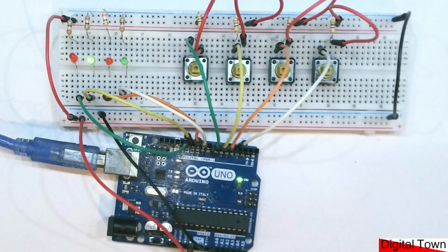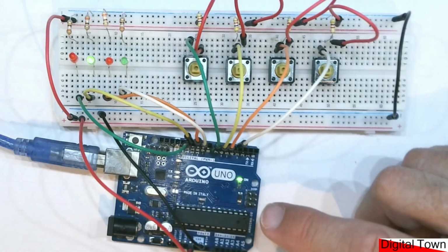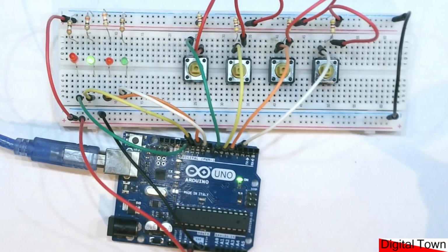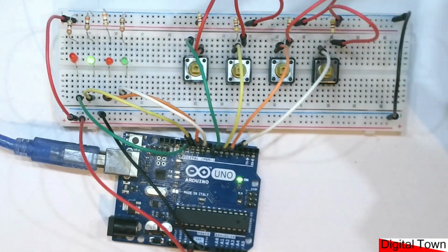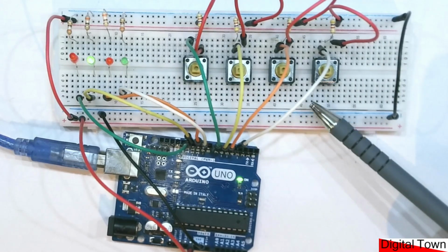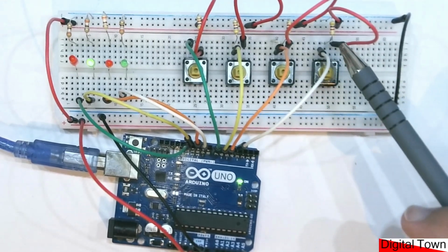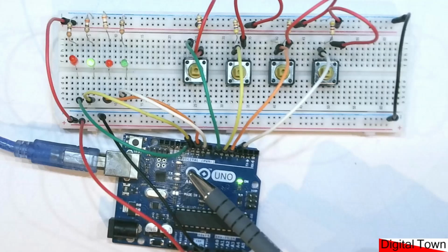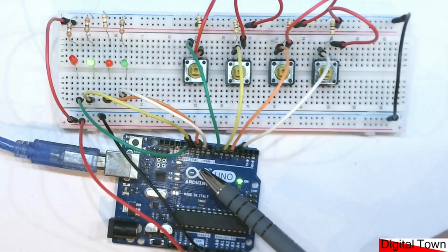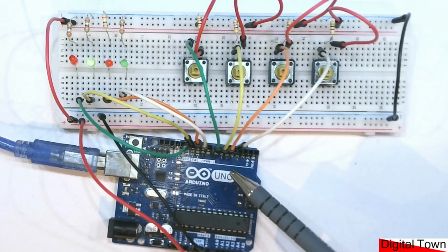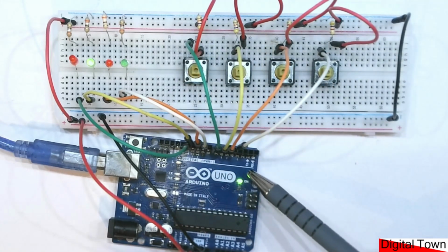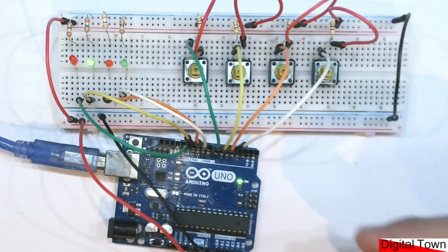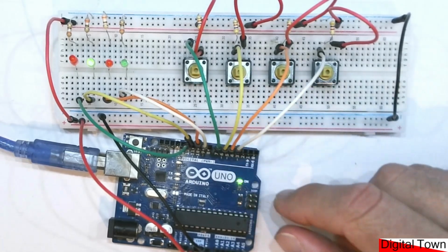So moving over to the webcam, this is the setup I have today. I'm going to be using an Uno for this example. Then what we have here are obviously 4 LEDs, 330 ohm resistors. Then I've got 4 buttons. Each of them are using a pull down resistor. I think these are 4.7K, something like that. I've got the LEDs going into pins 12 down to 9, and I've got the buttons going in pins 7 down to 4.